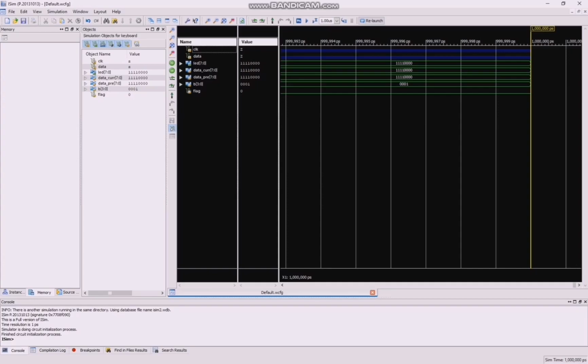When a key is pressed, the keyboard sends a unique code for that key to the controller serially over the data line. The serial data on the keyboard data line is synchronized between the keyboard and the controller by the clock pulses that the keyboard sends over the keyboard clock line.